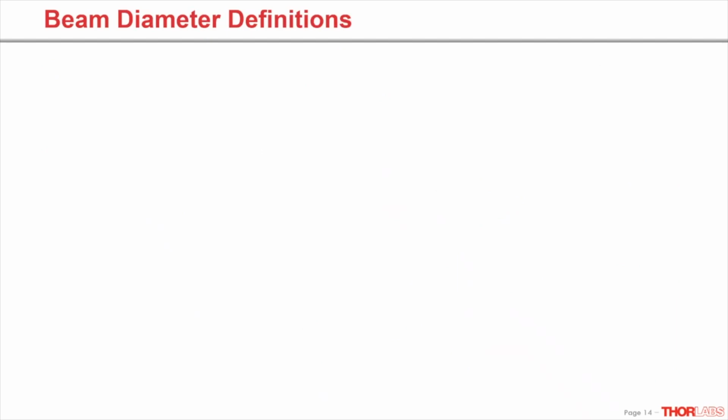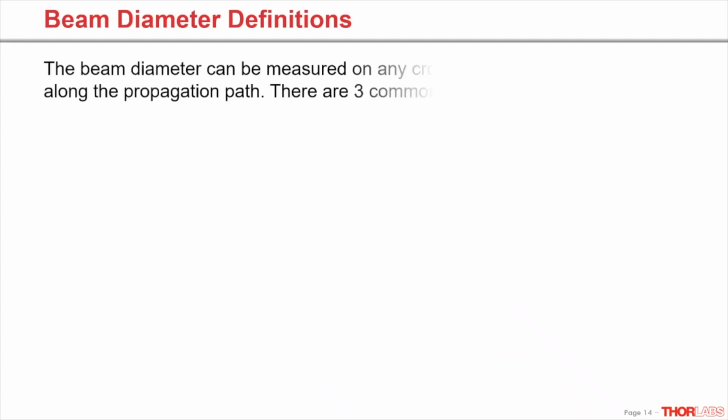So why is it important to know the beam diameter, or even more the intensity of the cross-section? On one hand, you may want to know if your beam overfills your detector. On the other, when it comes to higher intensity, you may want to make sure that your optical component or sensor can be exposed to the laser beam safely.